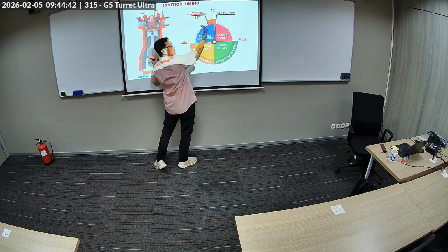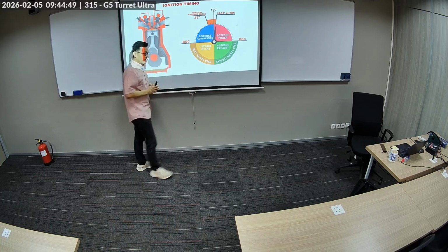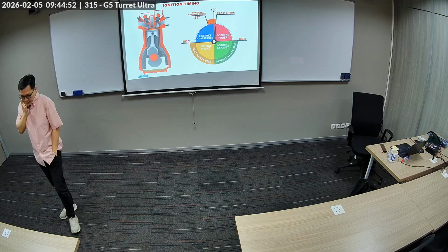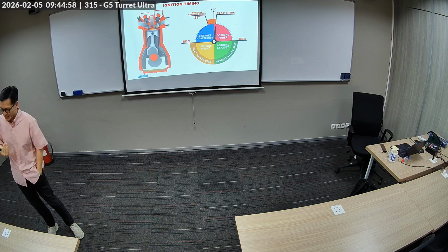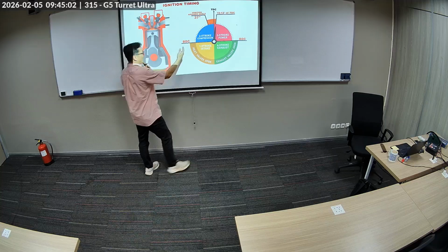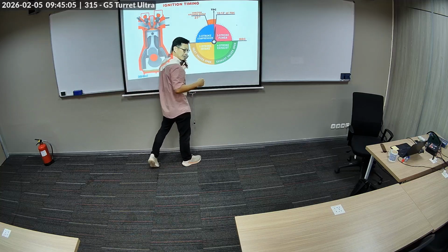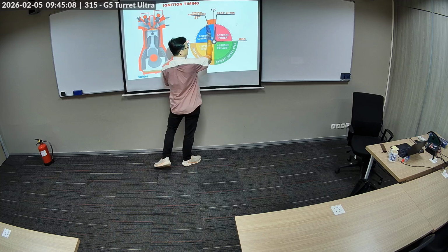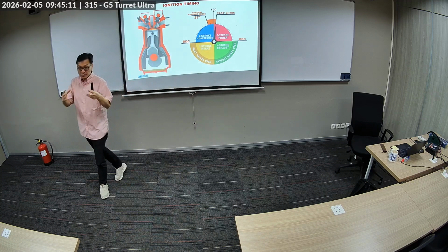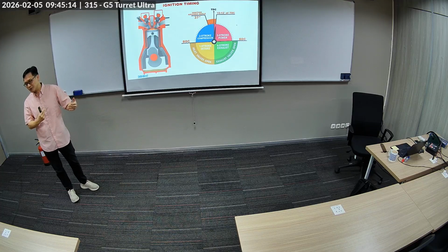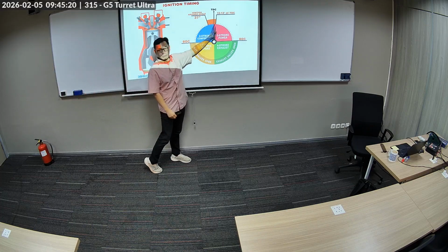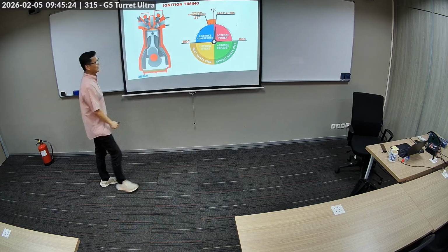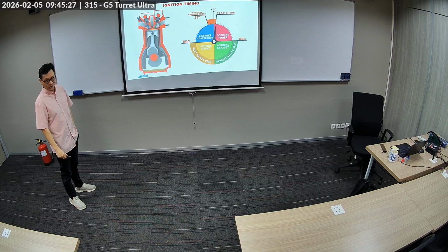So you can retard it, or sorry, advance it earlier, or you can retard it. Usually, when you tune the engine, you advance it as much as possible, but not creating knocking. The more advanced ignition creates more power, because you allow the flame propagation to fully expand. But if you have it too early, then it starts having local explosions before the top dead center, which is bad, real bad. Be careful. You can blow your engine easily if you are too aggressive on that.